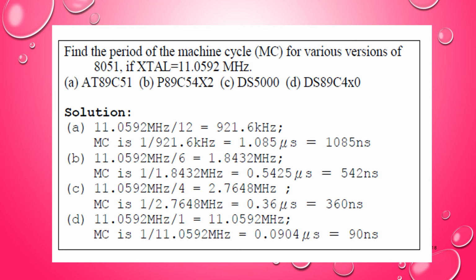Oscillator period wise, all these ACALL, LCALL, return, return from interrupt, AJMP absolute jump, long jump, short jump, they are all taking 24 oscillator periods. And even jump instructions like JC, JNC, JB, JNB, JBC are also taking 24 clock periods. So this is all about it. In the coming session, definitely while writing programs, we will use all these basic concepts associated with call, jump and delay associated with 8051. Thank you.